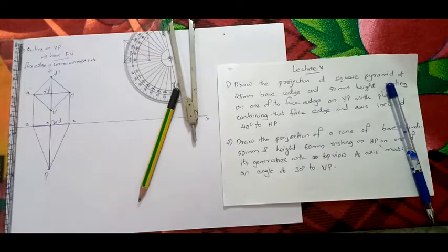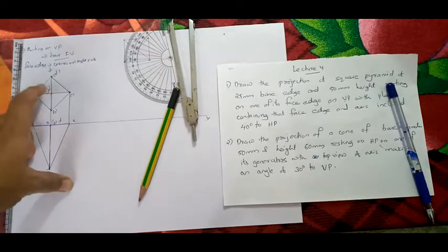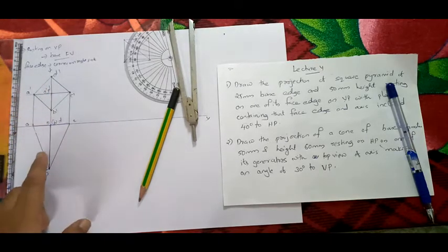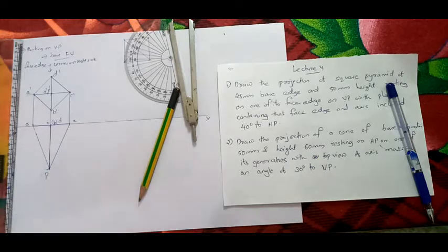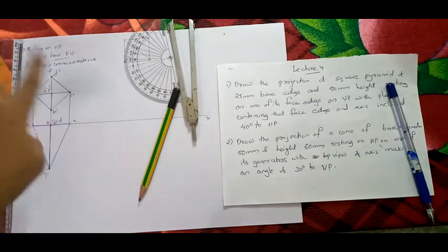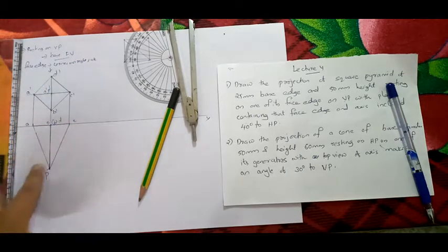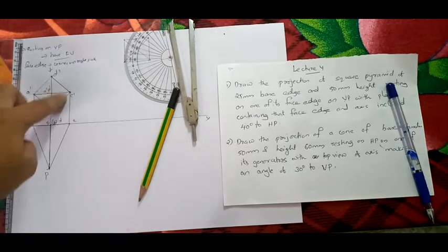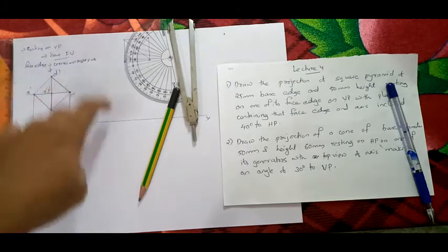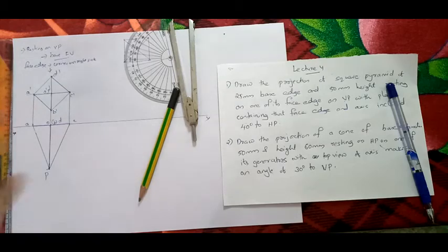First we rotated the front view. Here, if resting on VP, you have to give the first inclination to VP. Simply what I am going to say is, never give the first inclination to the base, always give it to the face. There is no meaning in rotating the base in the next view, you can draw that in the first view itself.